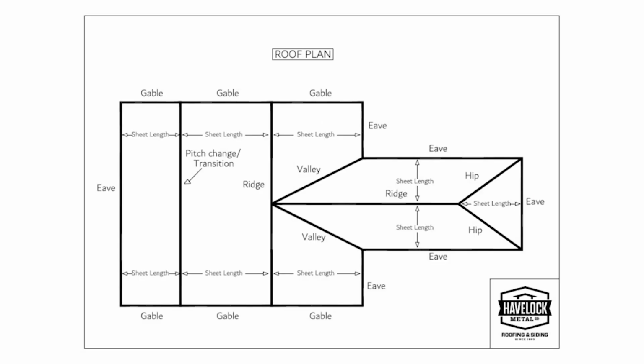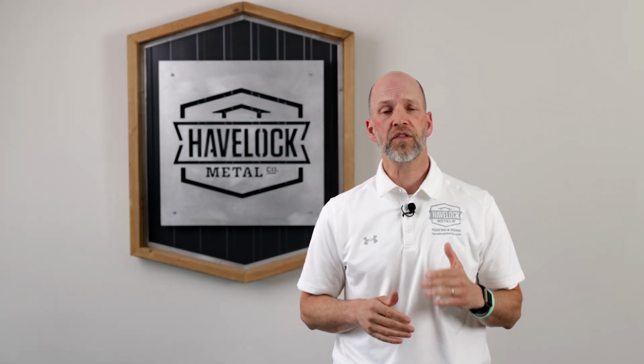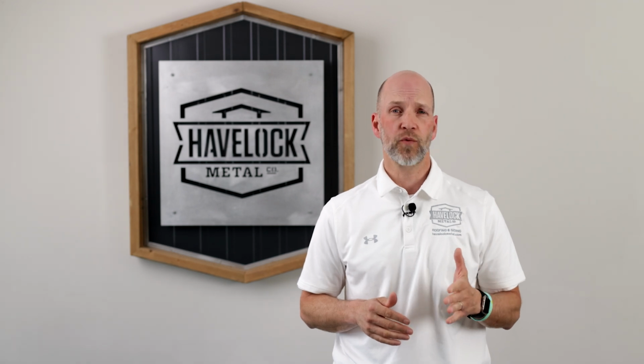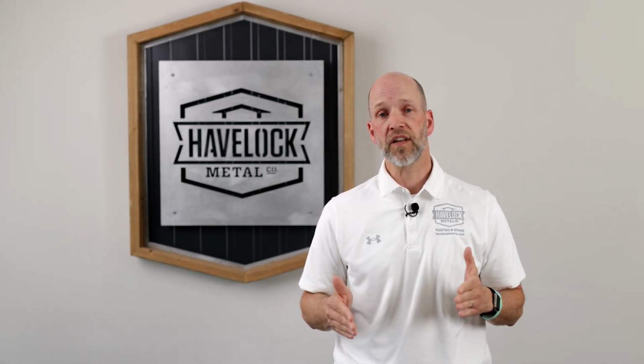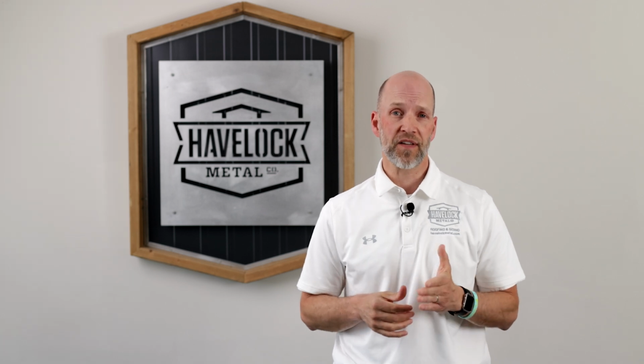You may want to sketch a plan view or bird's eye view of your roof. It is not necessary to draw to scale or even in 3D, so long as all the roof lines are present. Take measurements from the eave to the peak. Take care not to include any shingle overhang. This length will represent the length of steel we custom produce specific to your project.